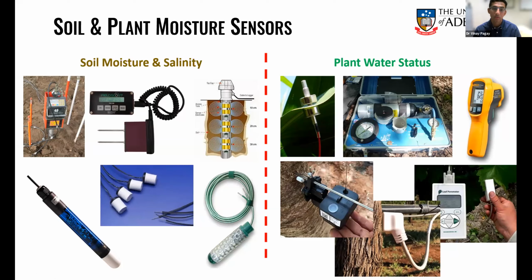And Ed touched on this, differences between soil tension with the gypsum blocks and soil volumetric water content with the capacitance probes. Now, the capacitance probes are really nice because you get the multi-depth measurement, and some offerings of these C probes can also give you things like temperature of the soil or things like EC estimates, so things like volumetric ion content. So if you're in a situation where salinity is an issue, you may consider a multi-depth C probe that gives you estimates of apparent electrical conductivity. So that's quite nice.